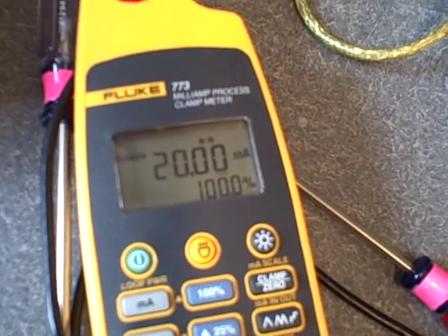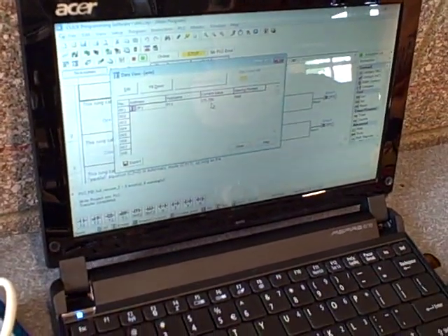It looks like we're consistently just a little bit high. I can actually take care of some of that problem through calibration. So let's step up here to 20 milliamps again. We're high here as well. Oh no, sorry, we're a bit low. 499. Okay, well maybe I'm happy where it's at. 16 milliamps should be 375, and it's 375.35. You know, to be within 1 degree in a thermocouple is doing pretty good anyway.